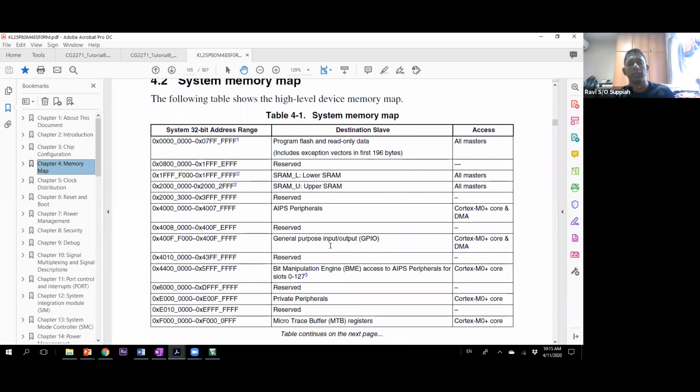Okay, so this is basically what is happening at the back end when you are designing a system. That means from a processor, you are putting together the memory, the flash, the peripheral blocks, everything, and you want to create a memory map for the system. That is where this memory decoding approach will come in, for you to understand how to place all these various components in the memory address space that your controller or your processor has.